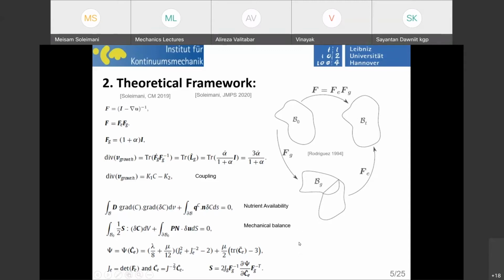If you multiply the denominator and the numerator by meter, you get joule per cubic meter. So this free energy is more precisely the free energy density, that means the energy per unit volume. And the stress is also something like energy per unit volume, because Newton per length squared is equivalent to energy per volume, since the strain is dimensionless.